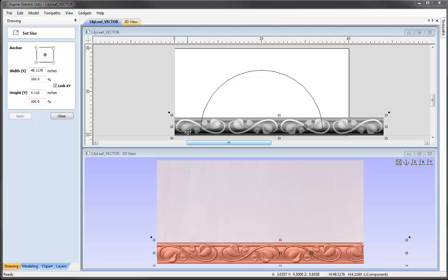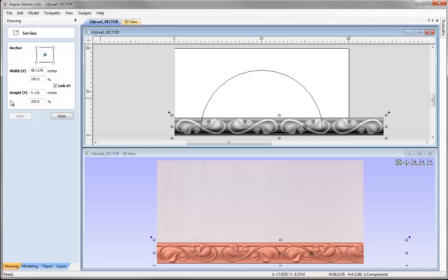And so that gives us a medium diameter between the inside and the outside edge of 32 inches, and this is what I'm going to use to scale the moulding. So I'm going to come in and just uncheck Link XY, as I only need to alter the width of the part so that it equals the length of my arc. To work out the circumference of a full circle, we do pi times the diameter. This is where we're going to use the 32-inch diameter, that medium value between 36 and 28, the outer and the inner edge, but I only need to work out the circumference of half a circle. So I need to use the equation pi times the diameter, which is 32, divided by 2 in order for us to get the half circle.